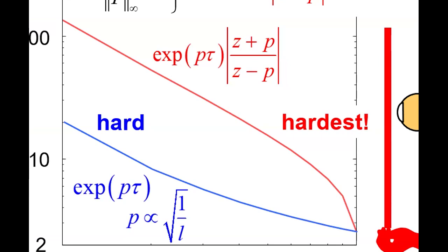So what's capital T? I didn't tell you about that. That's the transfer function from disturbance. If I'm sitting here, there's a little bit of noise in my vision, and it's how much that noise gets amplified to the error. The maximum magnitude of the transfer function from the disturbance scales like this when I'm looking at the top, and like this when I'm looking down here. So I've got to tell you what these things are.